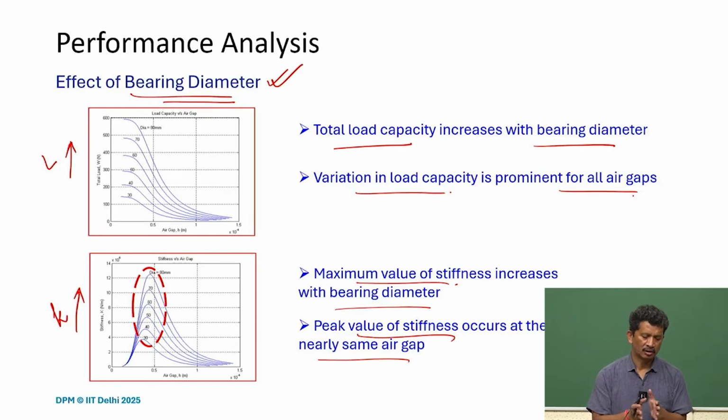When we are talking about pneumatic hammer or this pneumatic instability, the two things we are interested in are the supply pressure and the volume of air which is trapped inside. That is the reason we cannot have very big pockets on the bearing surface.